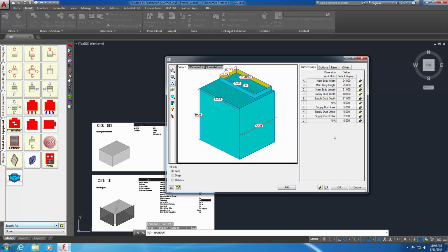To do this, click the Lock button to the right of the first dimension. The icon changes to indicate that the value has been locked. You may continue to select each Lock button individually, or you may lock all dimensions in one step. Select and hold the second dimension Lock button so that it changes from unlocked to locked. While holding the mouse button down, drag the cursor downward over each Lock button. As you do this, each lock symbol changes from unlocked to locked.